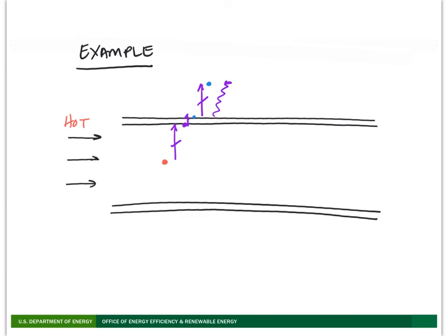There's one other form of heat transfer that we might also expect. We probably have some radiation to the attic walls or to the surroundings. We may also have radiation inside the duct, but it would be a relatively small contribution relative to the high velocity of airflow through the center of the duct. So we'll probably just leave that one off in our picture here. But it gives you a sense of the different types of heat transfer happening in the system.